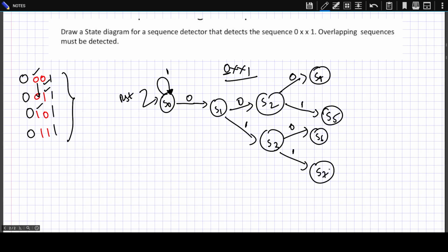Don't care about how many states you are getting, just focus on achieving the functionality. If there are redundant states, then we can easily identify them and get rid of them. But initially, while building an FSM, you should concentrate on the functionality itself. State S4 represents that we have matched 3 zeros, 0 0 0. In this case, we are only left with matching a 1.